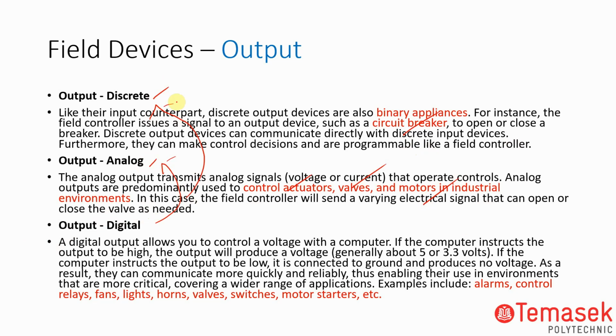Very easy. Discrete is the same thing, just higher power, instead of 0 to 5 volts, it can convert into whatever voltage, let's say 24 volts, which is an industry system, to 0 volts. So this is the typical logic conversion, and it's especially true when it goes to a lot of industry systems that are 24 volts.